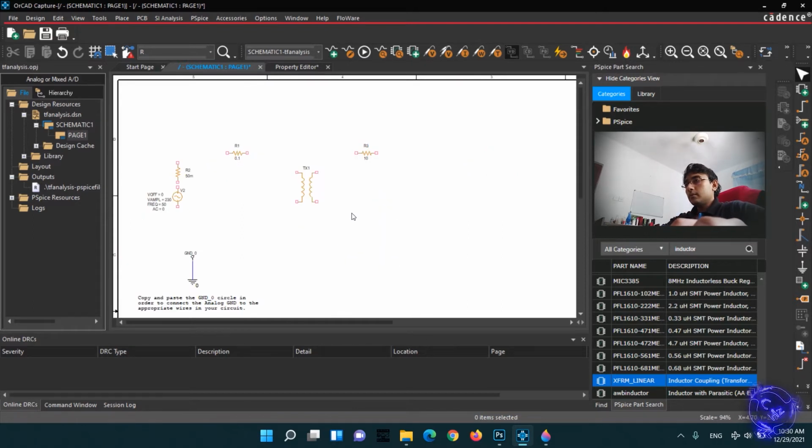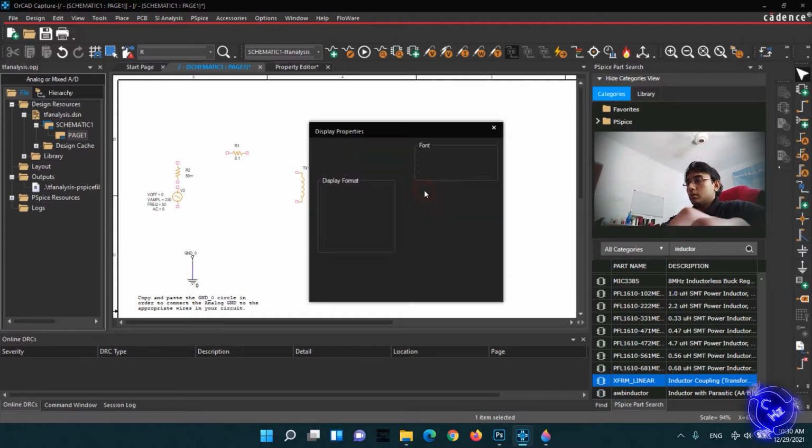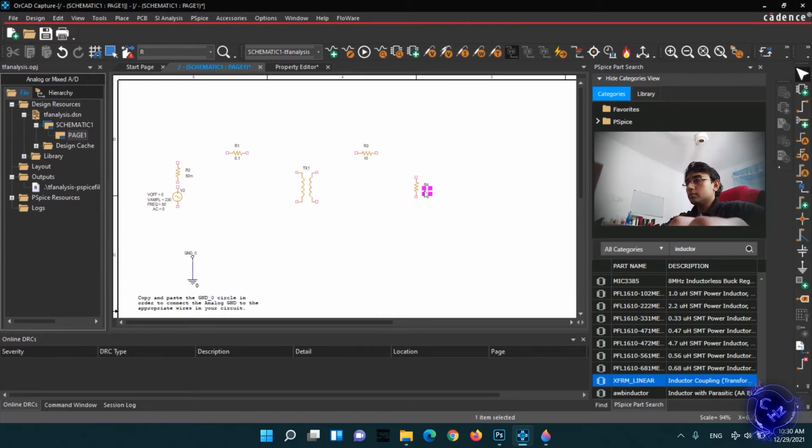Right, and for my load resistance, just press control and drag and drop. When I press the R button, it will rotate. So my load, I would like to set it to 1 kilo ohms, and pressing W will give me the chance of connecting these devices, these elements. And this is the ground.